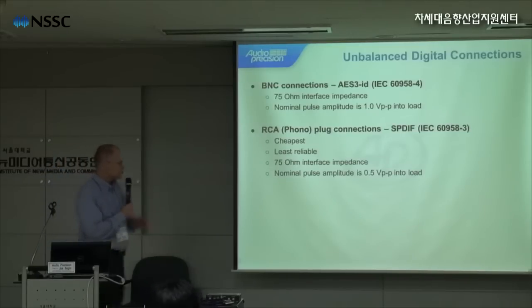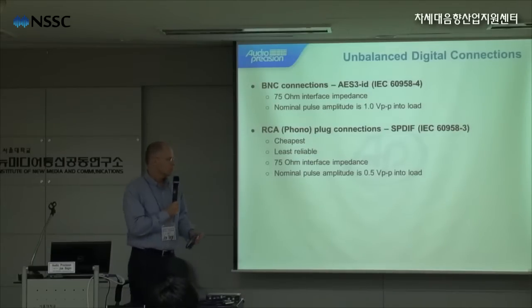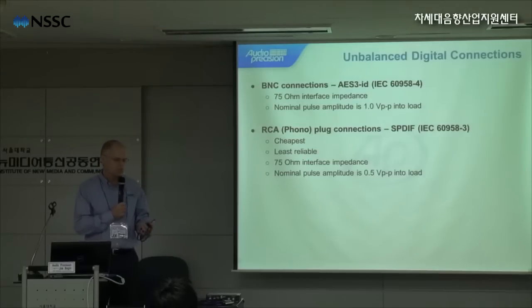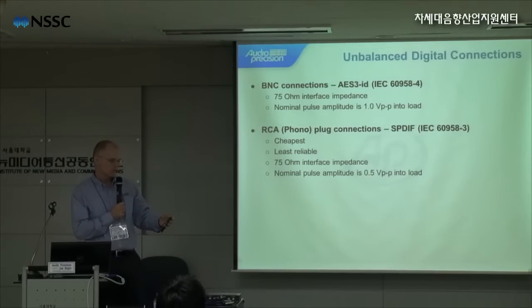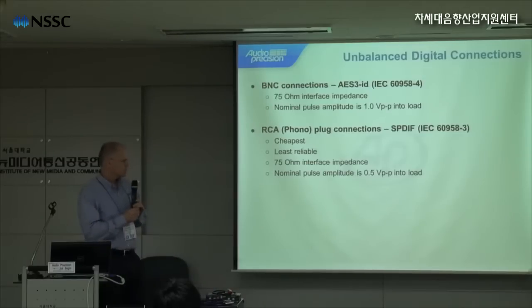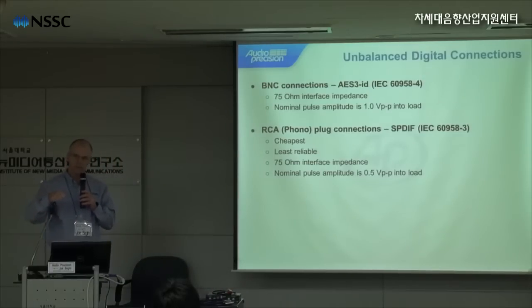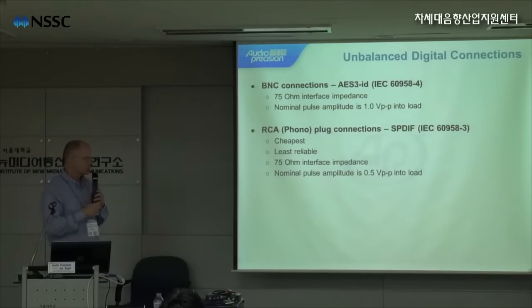And finally, there's the RCA phono plug connection, which is typically used on consumer equipment. We really don't like these cables. One of the problems with the connector is that when you connect the cable to the device, the first conductor to touch the connection is the signal. Sometimes cables can have a charge built up inside, and you end up connecting a high charge cable to a component, and you can cause damage. It's much better to have something where the ground connection touches first.